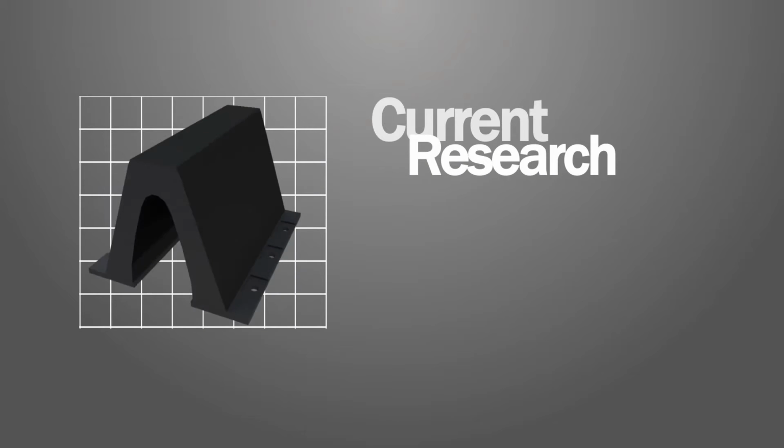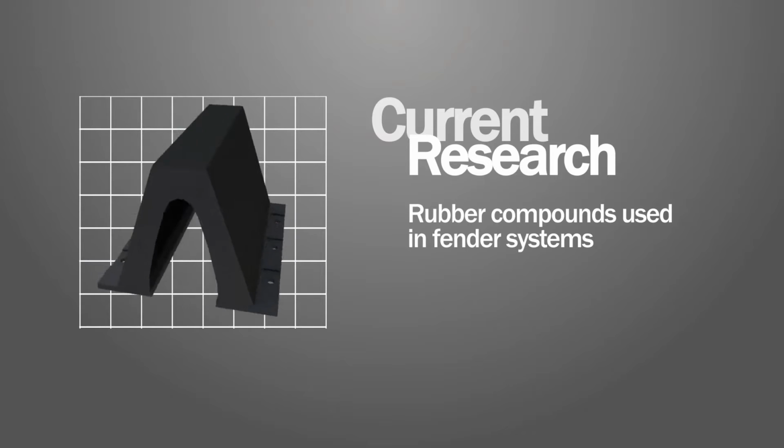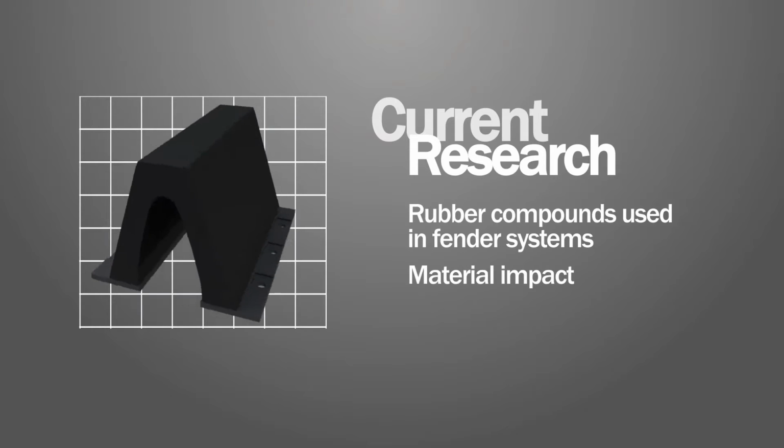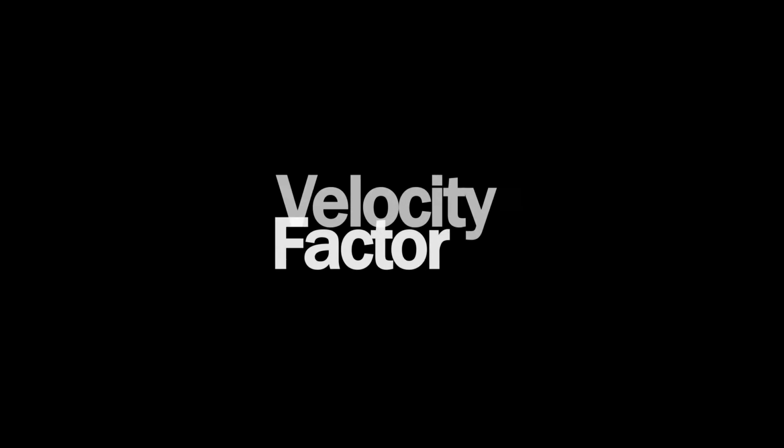reporting and calculating both. But current research into the changing properties of rubber compounds used in fender systems and the move towards non-traditional fillers mean velocity factor and temperature factor are now highly likely to have a material impact on engineering design and fender selection, as well as further implications for the design of other wharf infrastructure. First, let's take a look at velocity factor.